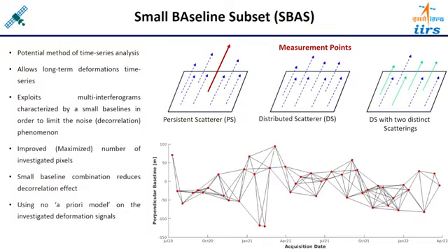So people are not processing all NC2 interferograms. They are processing much less than NC2 interferograms. Let us say out of 5000 we are processing only 500 or 600 interferograms, and the others we are ignoring. This is also an example of ignoring so many interferograms, only a few are shown in this particular graph. So you can ignore most of them and select only a few where you are comfortable.